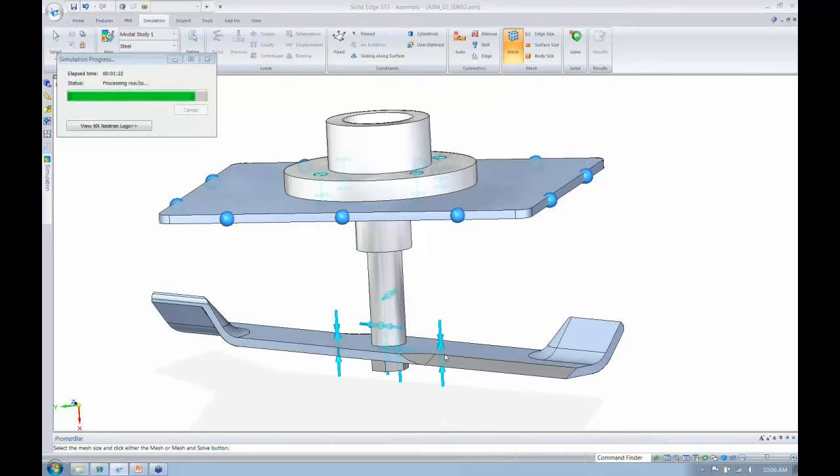Now, what I don't want to have happen is my natural frequency or any of the frequencies this thing's vibrating at to fall into that range, anywhere around there. My rule of thumb is that I want my first mode or my first natural frequency to be twice my operating frequency.